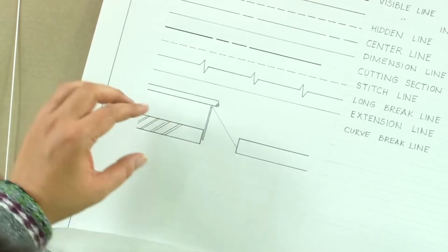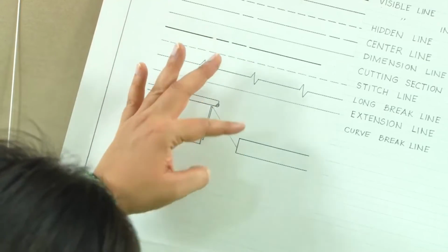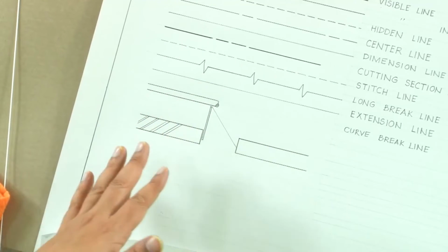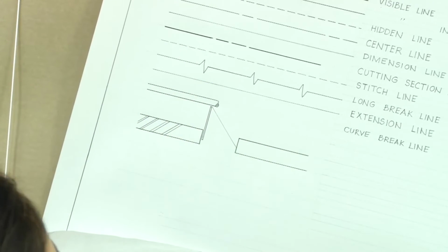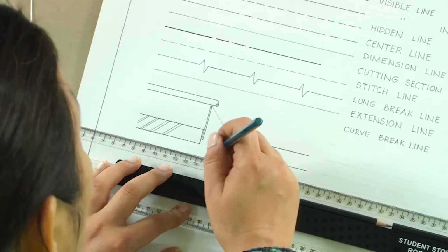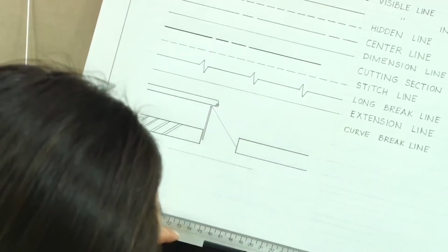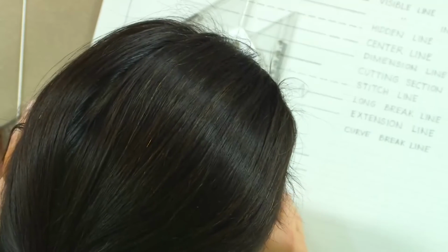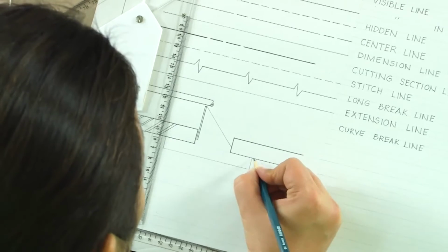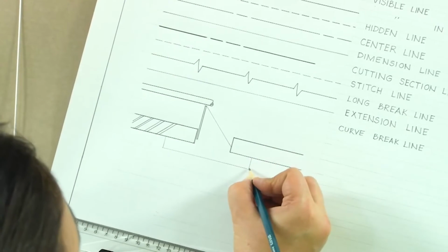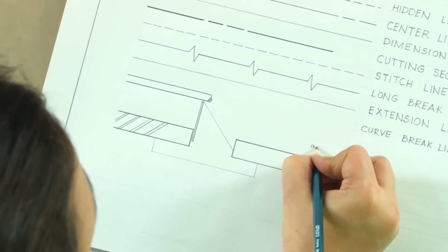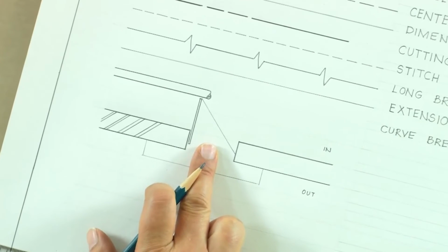Now this single door, if it does not have any step towards the inside or outside, implies that this is a door which is placed indoors inside the building. In case we want to mention that there is a step outside, we will make a line in the elevation which will be representing the step, not a staircase but just a single step. So this automatically represents that this is the outside and this is the inside. So this is the representation of a single door.